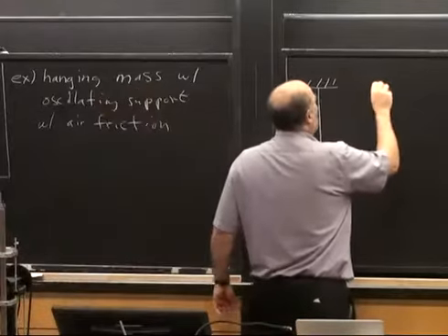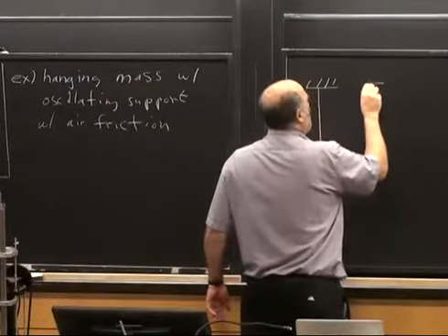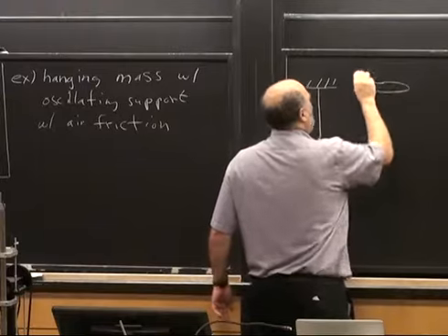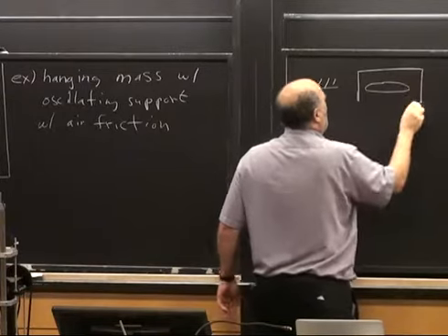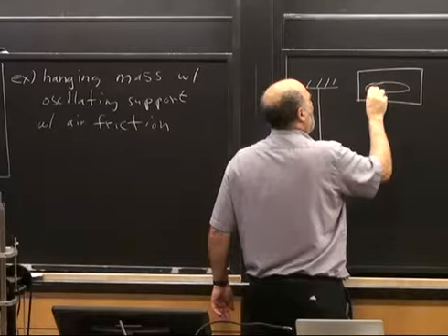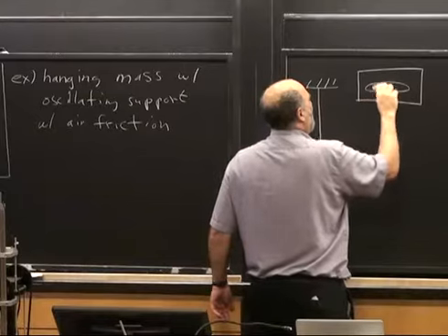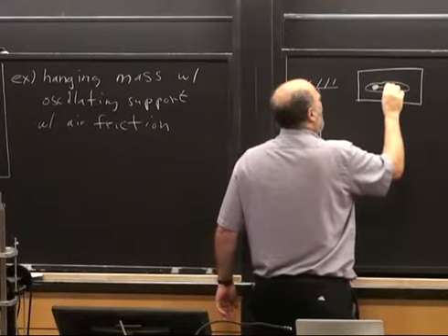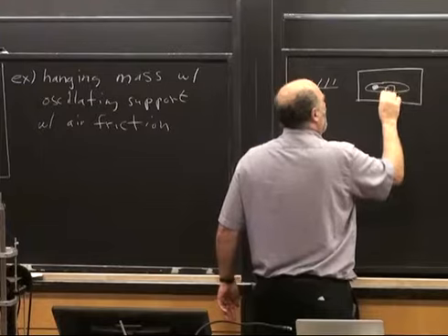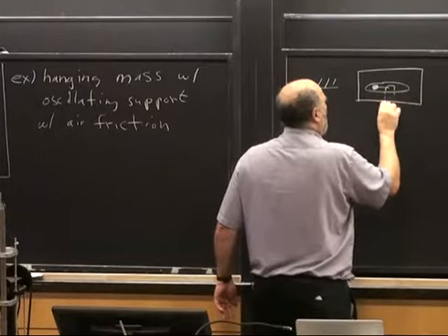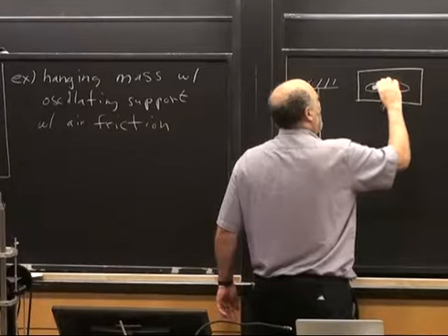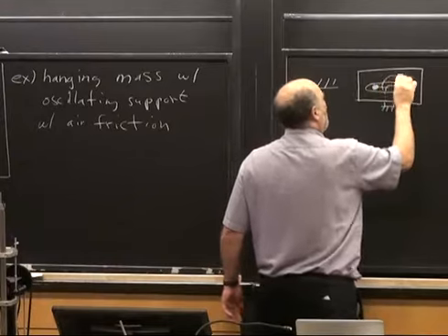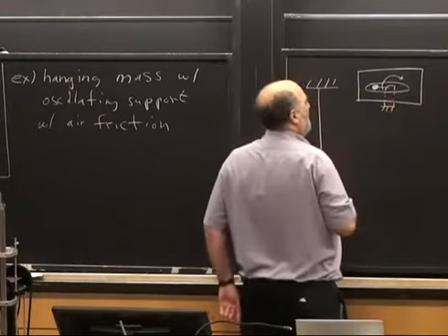And then we're going to have this support, and the support can be using the same Scotch yoke design which is used in that little machine there. There's a pin here, which is connected to a lever, and this thing is connected to a base like this, and this thing is spinning in circles, so this point goes up and down.